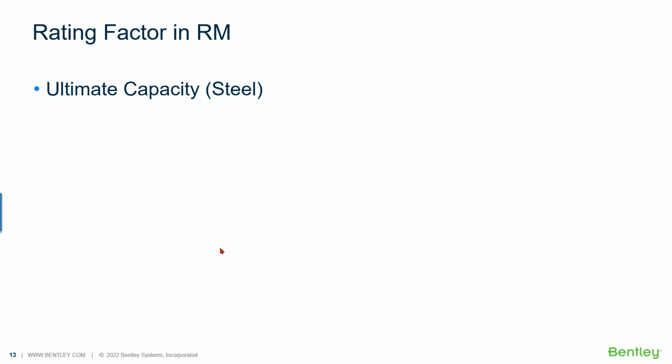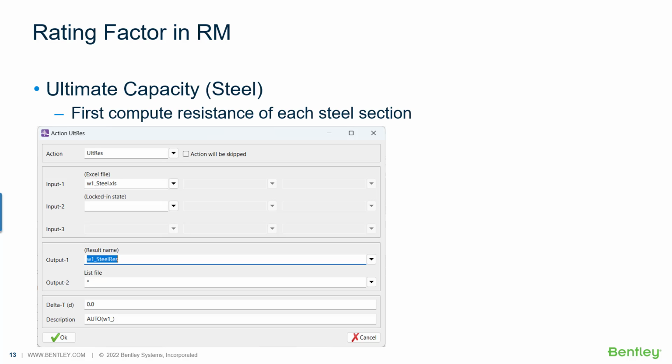For steel, it's a little more complex because you know that the behavior of the steel is more complex depending on whether we are in compression or in tension. In tension, it's very easy because we can go until the ultimate strain, even in the plastic area. But in compression, we have to take into account other effects, and in some cases reduce the maximum capacity, due to warping of the cross sections or different side effects.